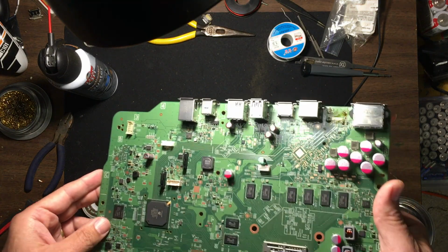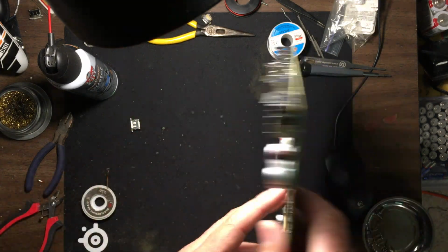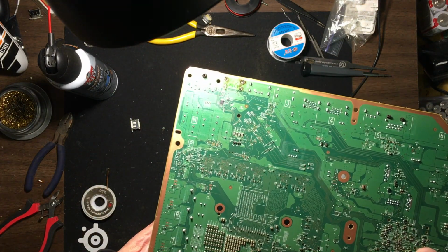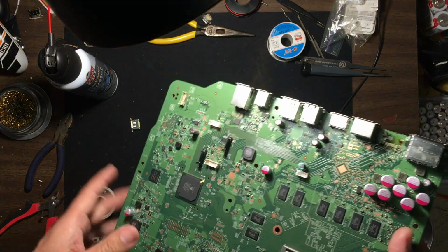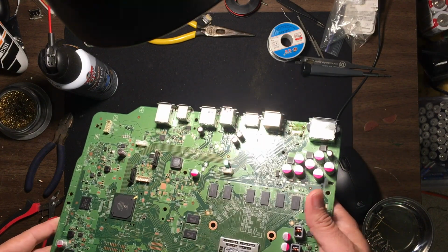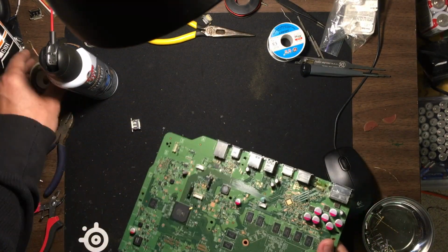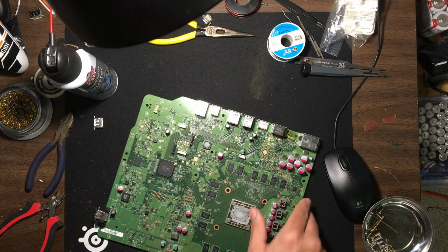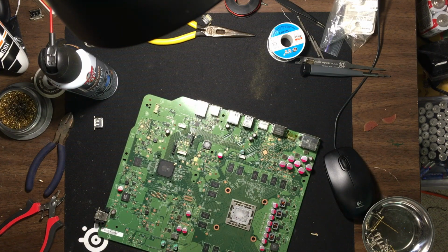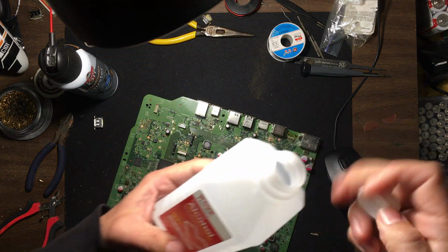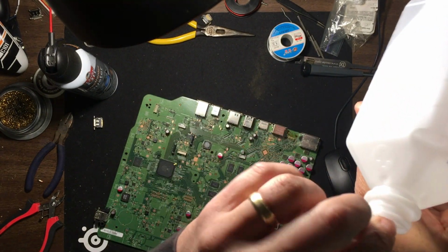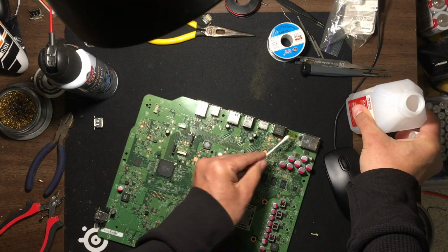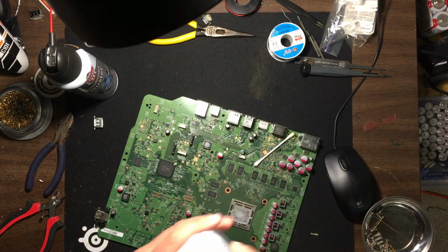So what I'm going to do now is clean this up really good so that there's no flux on it, so that it's a nice surface for applying. I'll actually put fresh flux on when I'm resoldering, but you can see it's all burnt and it's crap in there. So we're going to clean that off. And we do that with, like I said 1,000 times before, some rubbing alcohol. I usually use 90%, and put it on a Q-tip and then dab it a lot. It takes some work to get it off, but you basically just run it across here. So I'm going to do that next.